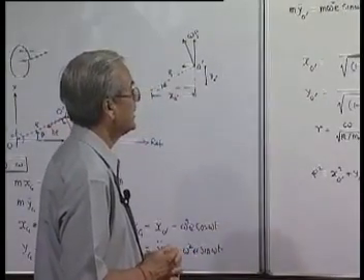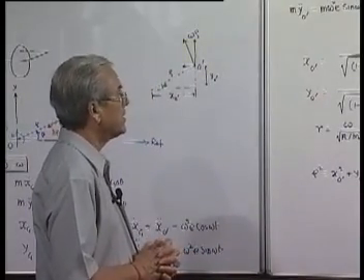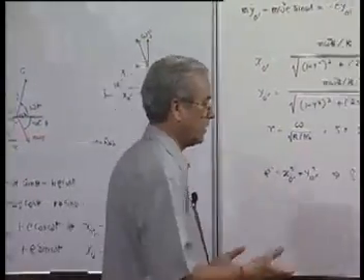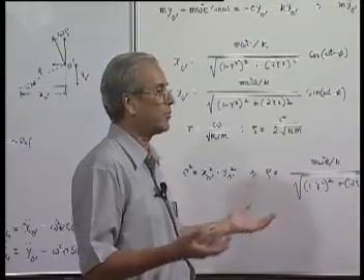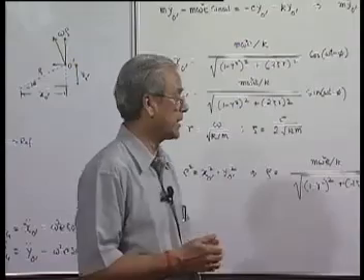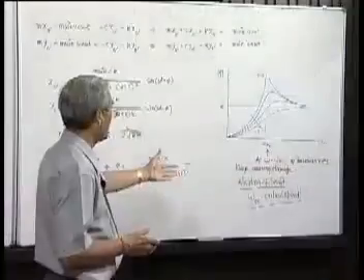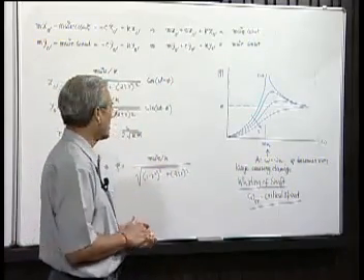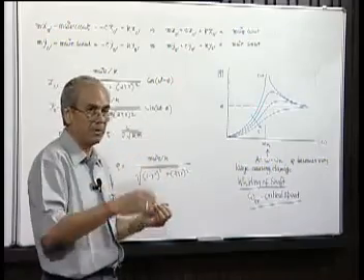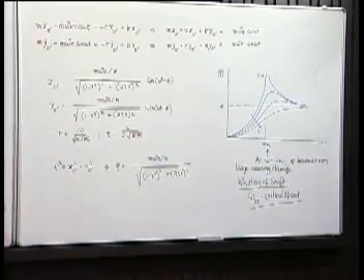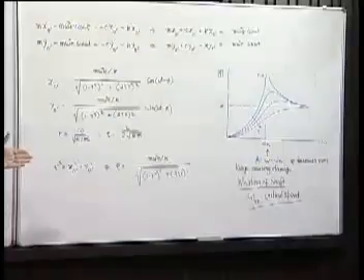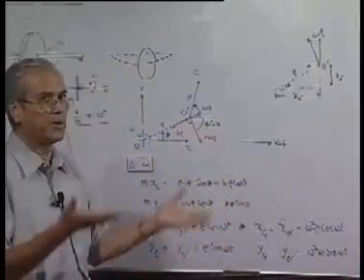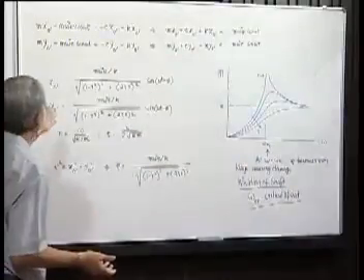Sometimes it is found that the critical speed is low and the operational speed is high, for example, like the alternators in thermal power plants, where the shaft rotates at a higher speed than the critical speed. In such cases, to avoid whirling and damage, the shaft is quickly accelerated through the critical speed, so that it does not get enough time to build up large vibration and large deformation of the shaft. So, the simplest situation is very similar to what we get in the behavior of a simple spring mass system when some damping is there.